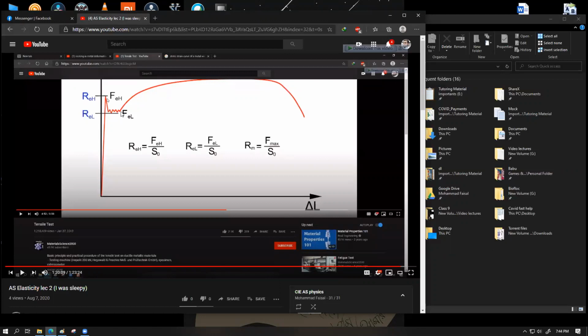Well, try to think about it. If we replace that metal specimen with a piece of plastic, would you get that much high force? No, sir. Let's say the machine is capable to put much higher force, but would you get this much high force? Or would you get this much of a steep line? The machine is capable to give all the forces that you want. But if you choose your specimen to be a weaker material, would you be able to get that much force? I mean, would the machine be able to apply that much force onto the specimen? No, sir. So how much force this machine can apply onto the specimen is very much related to what you are trying to stretch out. If the specimen cannot resist that force, the machine cannot apply that force.